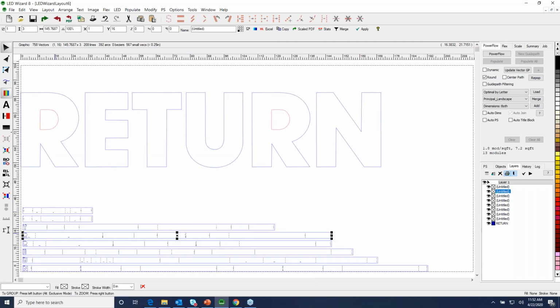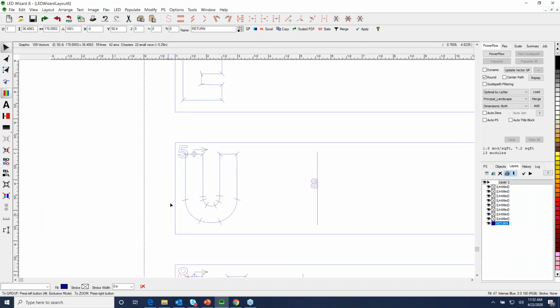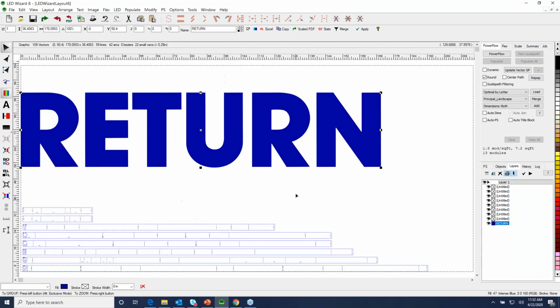If I click on this R pattern, this is 145.7687 inches. And if I looked at the total perimeter of the R, it would be the exact value minus 1/2 inch. Essentially that's how this works. You plot this out, you strip down the returns, you tape or paste the pattern up to the returns, and it tells you exactly where to bend.